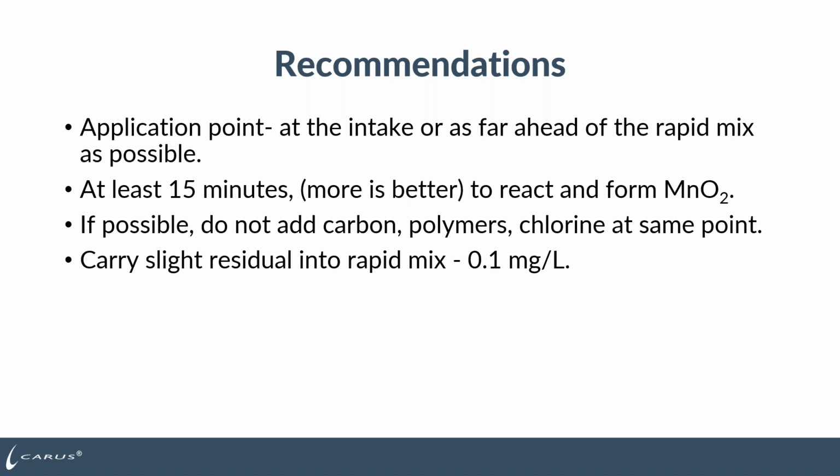And then obviously you want to try to avoid adding chlorine at the same time as permanganate, because as you form THMs and HAAs, once that THM or HAA forms, it's no longer reactive with permanganate and it will be there. So you really want to do pre-treatment with permanganate to remove those organics, and then add your free chlorine at the back of the plant for your disinfection. And like I mentioned, we'll test for permanganate residual downstream of our application point to maintain control to make sure we're feeding enough permanganate.